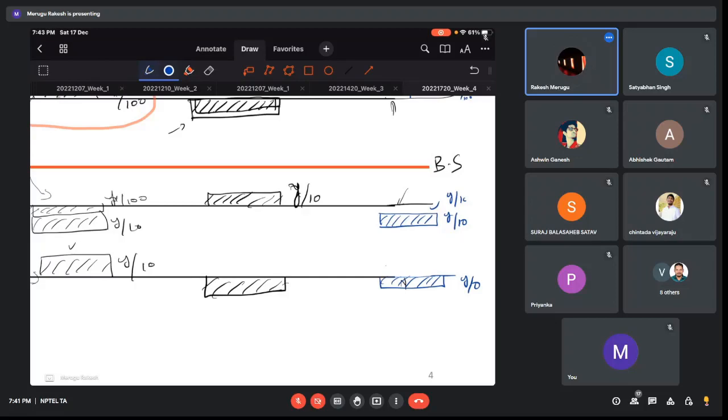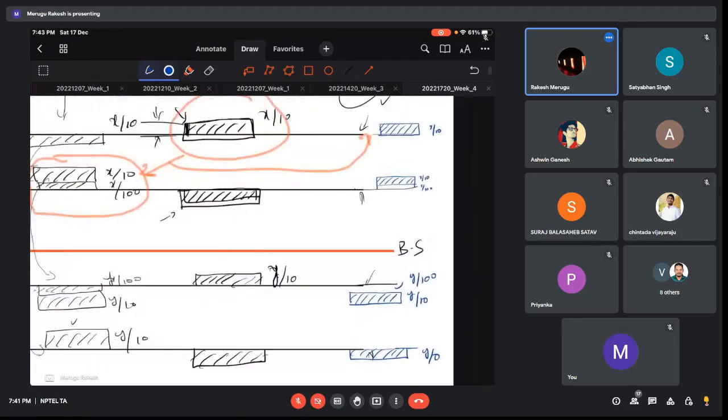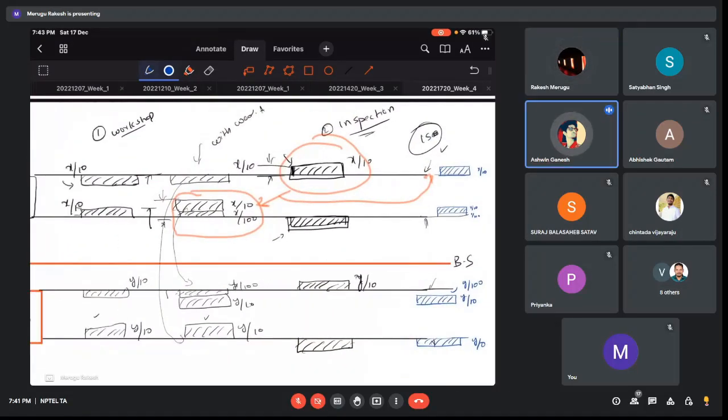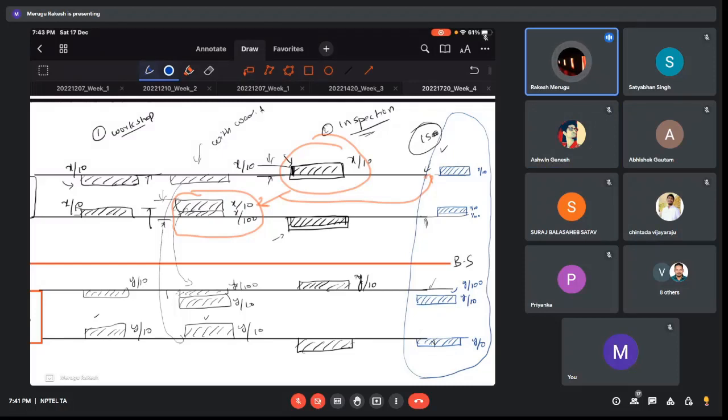And this is the work tolerance that we produce. So for inspection, there is no wear allowance, because they are already outside the desired tolerance. Even if they wear out, that doesn't affect my product quality. But in ISO and workshop, we have to provide wear, because they are within the limit of our selection.